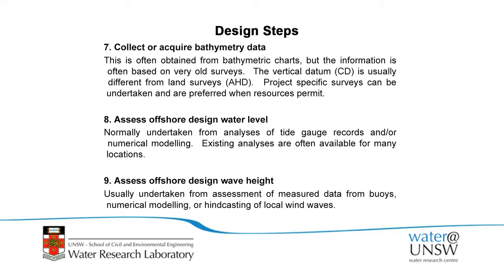So on to another design step: collect or acquire bathymetry data. That's a bit harder to get. It's often obtained from bathymetric charts, but the information on those is often from very old surveys. Certainly even today, for some of the mid-north coast of New South Wales, the bathymetric charts, if you read the fine print, were acquired about the 1850s or thereabouts, believe it or not.